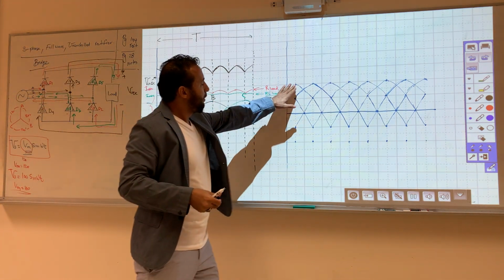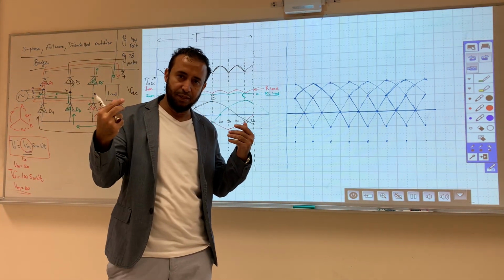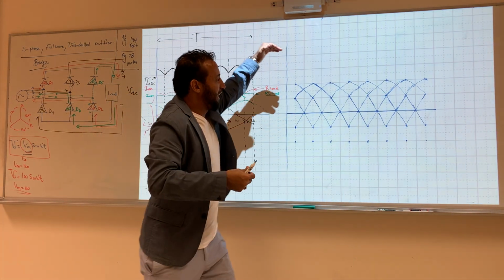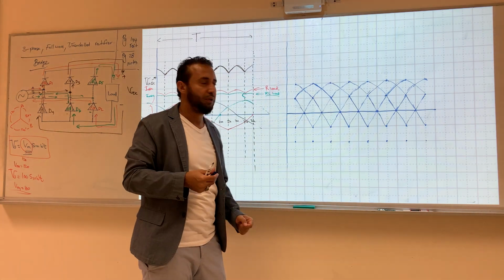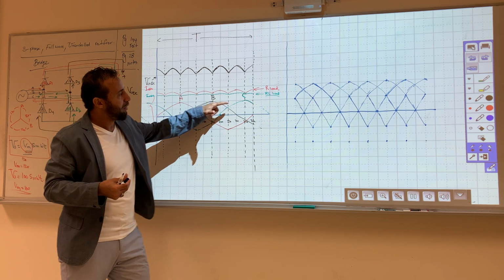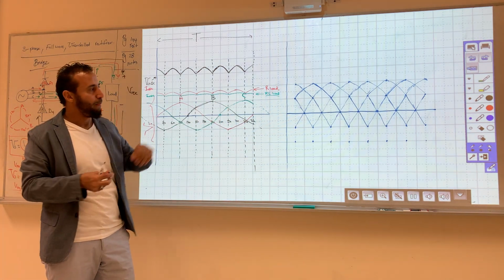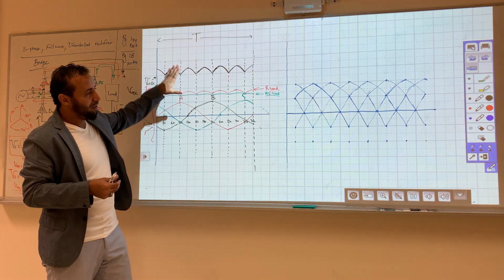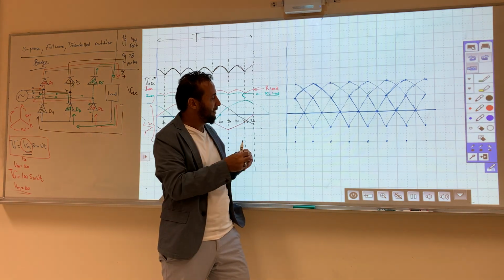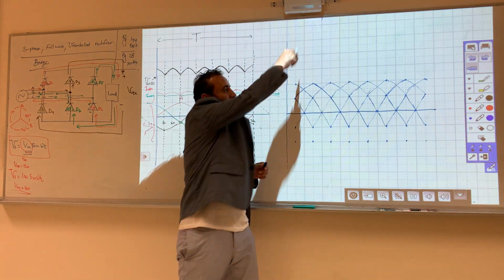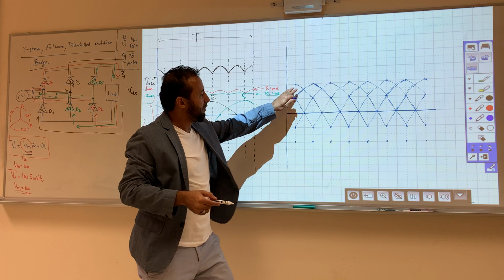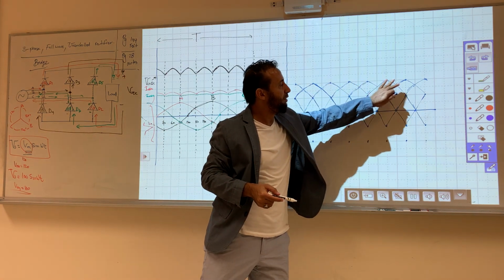This one here, if you look at it, remember last time in the three-phase half wave, we said that we will take the highest point. We're gonna do the same. When we draw this, I told you that my output will be the highest point. Okay? Now you guys see here? That's why we draw the peak right here. We said it's the high peak. See the peak here? From this x-axis, that's my peak. So you're gonna look at the highest points from the top. So one cycle, your output will be these 6 pulses.